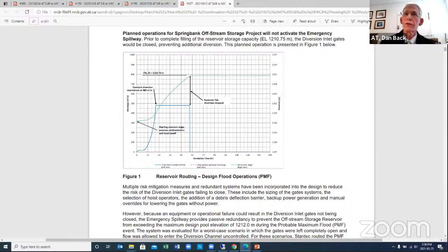That involves integrating the motions that occur during the design earthquake and establishing how much of that motion exceeds the pseudostatic factor of safety, and summing up the motion that would come out of each of those pieces from the time history of the earthquake. And that gives you an amount of settlement, loss of freeboard, if that's the term you want to use, that would occur during the design earthquake event.